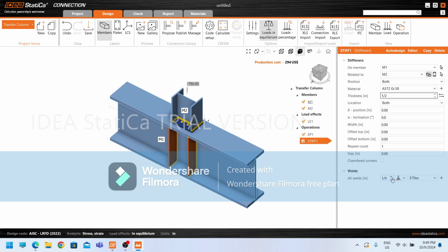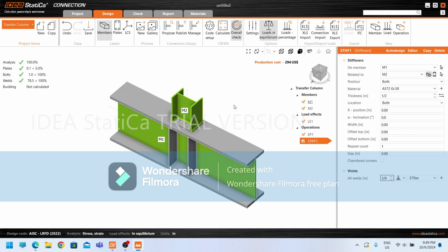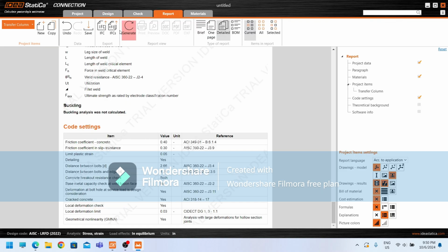It should be more than 5/16 or 5/8 times the plate thickness as per the AISC manual; I don't remember it exactly, so you guys need to check it. Since we do not require a stiffener, it's not actually calculating the stiffener.